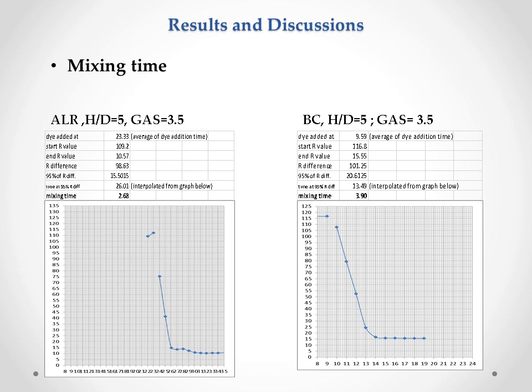The mixing time can be defined as the time needed to obtain a specific degree of homogeneity, and it is correlated with the specific power input and the geometrical parameters of the bioreactor. We used a blue dye to measure the mixing time by recording a video from the adding of the dye until the desired homogeneity. Then we processed the obtained images in a software called ColorMax, which is a color analysis software built by my supervisor. It helped us to collect data and produce the mixing time curves.